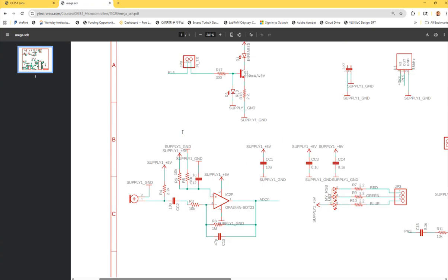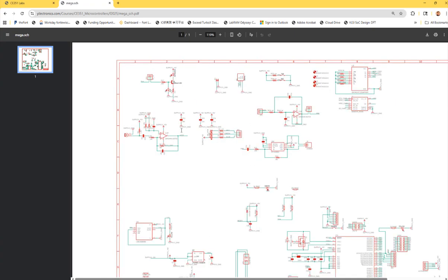All right, a couple things because I changed the deadline for Tutorial 5 Tactical 3 to tonight, and some other things I found from other students. The IR light doesn't work well for a black surface. I've done a very similar experiment in the past for circuit 1, using an IR pair to detect the track. The track we used was a black tape on the table. Whenever it detects that black tape, it gets turned off because it's not reflective. So eventually, you have to use a light color surface.